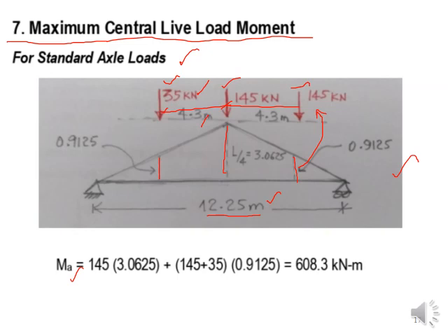Okay, so there may be a case that one of the wheels can get out of the span, and you are calculating it for just 2 wheels. Whatever, you have to move this wheel on the right or left side of the whole span of your stringer, and you have to calculate the position where you are getting the maximum answer. For this particular case, the solution is given, you have to do it by yourself. Okay, they have given the maximum value for this particular situation.